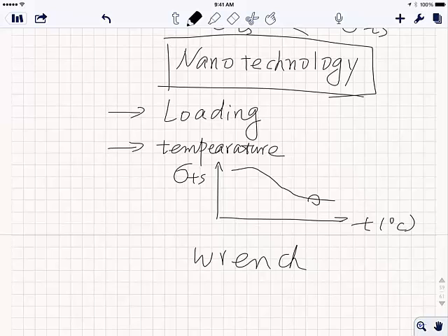Another example is probably one I told you guys already. Everybody chews chewing gum sometimes, right? Initially when you take it out of the package, it's very hard, right? When you chew it for a long time, it becomes soft. And then when you go to a drinking fountain and drink some really cold water, what happens? It becomes hard again, right? So at a lower temperature, your strength or your modulus is higher. At a higher temperature, it's lower. Easy, right? So therefore, when you consider endurance limit, temperature matters. At a higher temperature, it's going to be lower for sure, right?